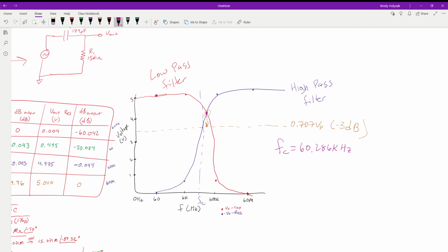Then they would take a band pass filter, which we haven't talked about yet, to use the middle frequencies, so it would strip everything else out except for the range of frequencies that they wanted, and then that would be sent to an amplifier to amplify those, and then the lights would kick on when they reached a certain value of those. Then they did the same thing with the highs, the high frequencies. They selected just a high pass filter and said at this frequency up, we want these signals. Anything below that, we're going to reject it. So they were able to break up the spectrum of sounds to get these different signals. Now they have 3 distinct signals, 3 distinct patterns of what they're looking for and what they're amplifying.